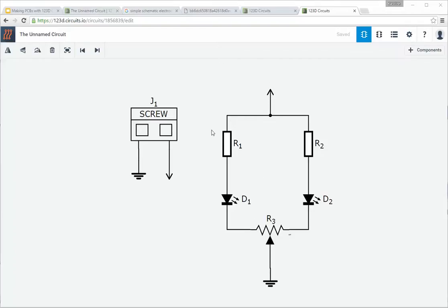What we did here by adding this screw block is that the screw block lets you plug in external power sources. So we connected one side to ground and one side to voltage, and we made sure that the voltage source is equal on both. If you click on it, you'll notice that a box will pop up that says VCC, name 1.